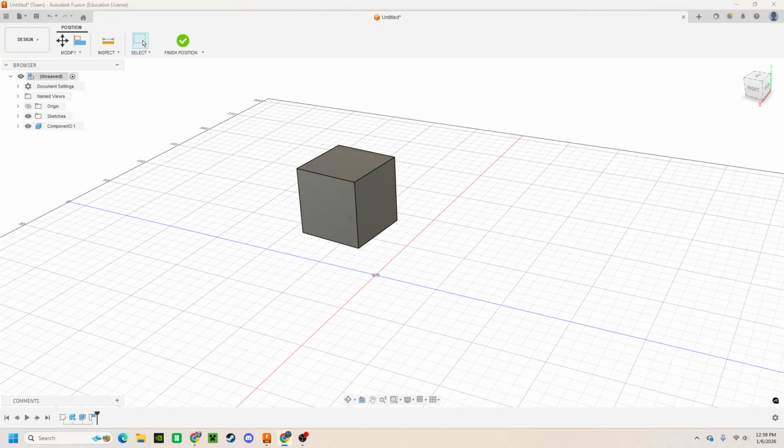The next tool, Align, is very useful when working with assemblies. It allows us to align parts of faces, edges, and points with other parts in our workspace. Press the Align tool in the top left corner. Try hovering over a face. You can see that it has different starting points that we can work off of. If you press and hold Control while hovering over a face, you can lock your cursor, which helps select which part you want to select.